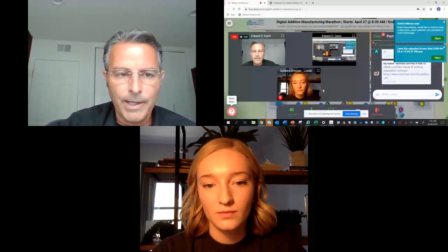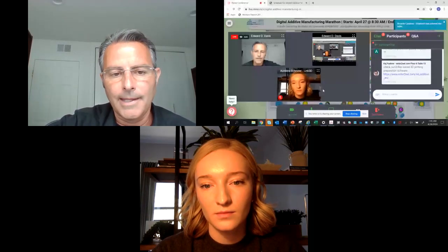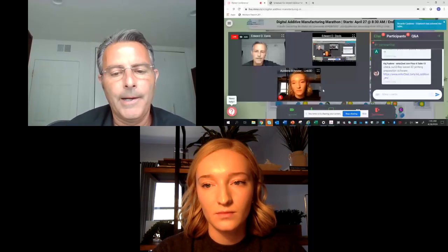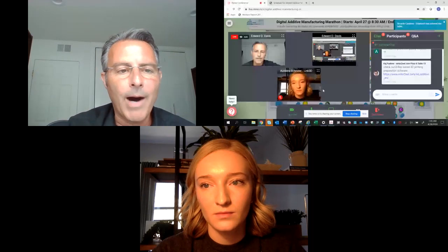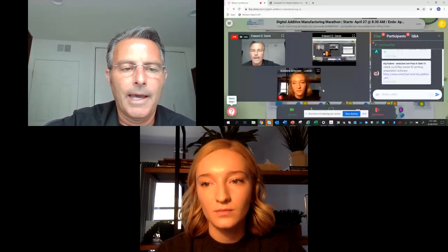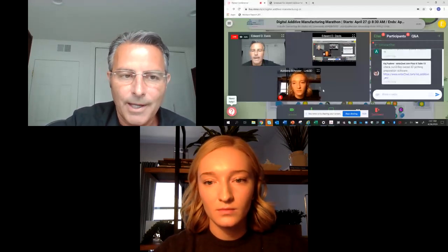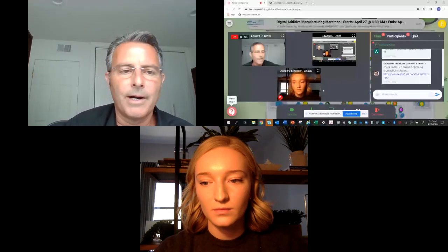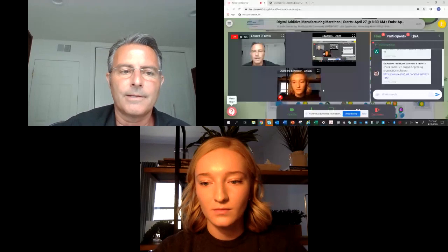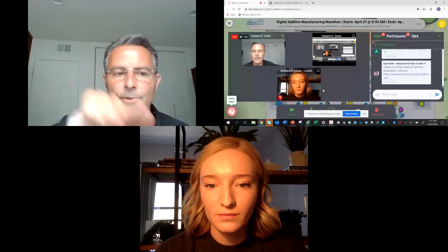What I can anticipate in the future is this process control software that I showed for tuning the process needs to incorporate some models of behavior of the thermal process. And if, in fact, you have this model of behavior, it's a simulation, and you measure the part quality coming out the end, if you provide feedback from the part quality itself back to that process control software, you can start to correct those models.